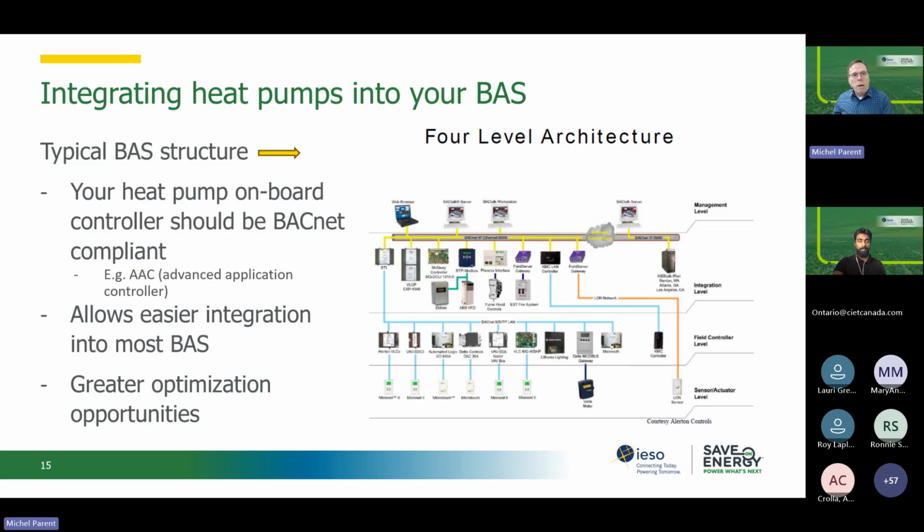So you've got a heat pump, or you're considering a heat pump, and you want to integrate it into your BAS. Quick overview, your BAS is likely a 4-level, or 4-layer, system, as you see here. You want to make sure that your heat pump has a field level controller.